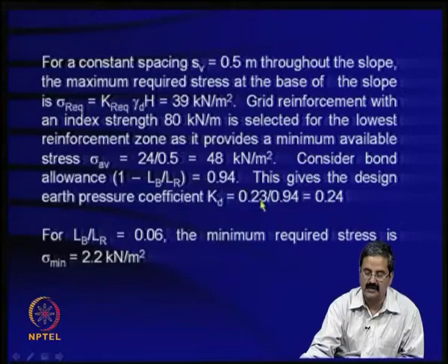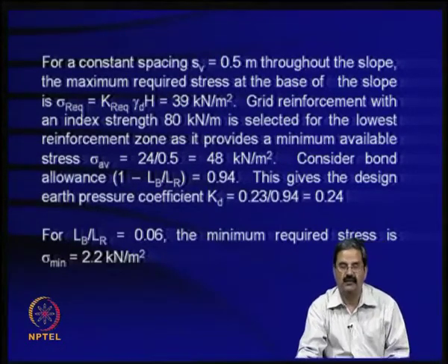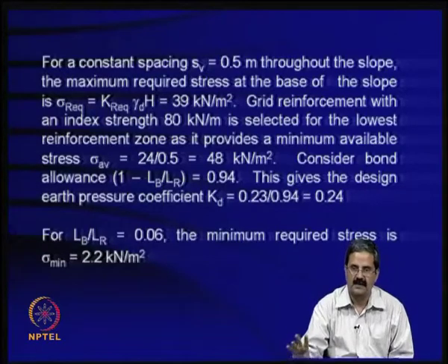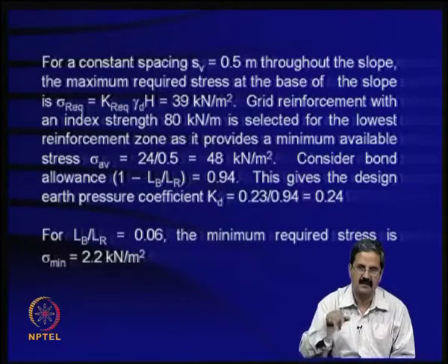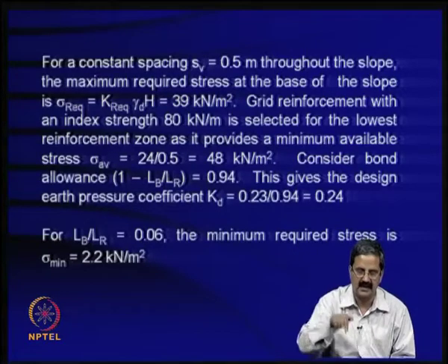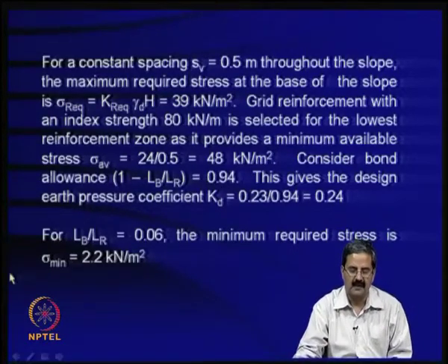as I just mentioned, the reinforcement coefficient like 0.23, which we obtained in the previous step, should be slightly corrected, and this will become 0.24. Essentially, this is because of the orientation effects. The reinforcement should be placed in the direction of tensile strains for the maximum benefit, and for the bond it should be placed at 90 degrees to the vertical stress. But in the field condition, there is an intermediate angle, because of which the K required has to be corrected, it has to be increased actually.